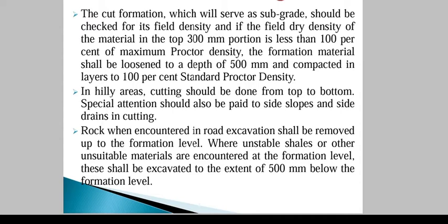For example, if you are going for an expressway or national highway, then instead of cutting the entire hill, they'll drill a tunnel. As the project funding is more, they can afford tunneling in the hill or the ground, and they'll provide a passage and reduce the total distance instead of the round. If it is taking 2 to 3 kilometers, within 400 to 500 meters of tunnel they will cover it, and overall maintenance and vehicle operation cost is less, right. So that is one of the methods.